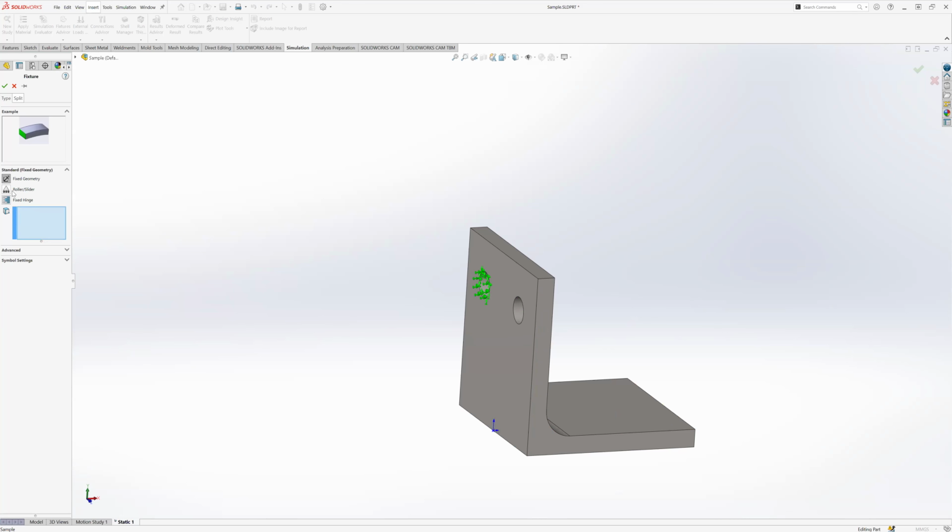So the next one is roller slider. This is also a very common one. If I apply it to a face like this, it works kind of like the picture here, like that roller constraint I demonstrated in 2D. This body, or this part, can slide on this face, but it cannot penetrate through this face, and it cannot come away, if that makes sense. So those 2 faces are always coplanar, but it's free to translate, and also free to rotate about that face.